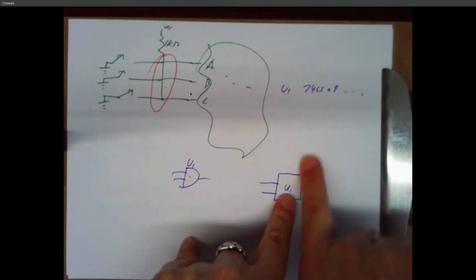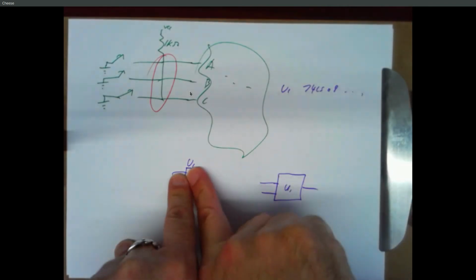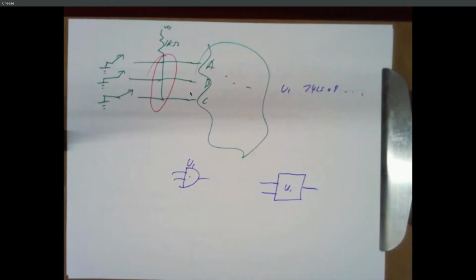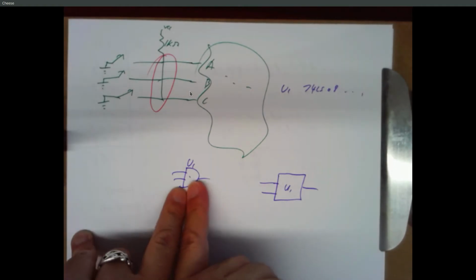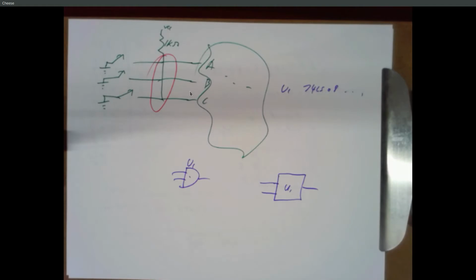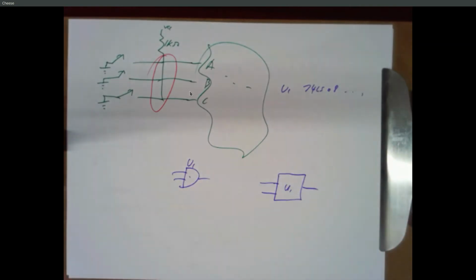This requires a lot of work to know what your circuit does. The point of having the component ID block with the component numbers like U1, U2 is so you can actually wire the circuit together. But to understand logically what it's doing, all you need is the logic gates, and that's the part of the diagram that somebody would look at to figure out the behavior of this circuit. And then if they're actually putting wires into a protoboard, they'd use the U numbers and the pin numbers and so on. Does that make sense?